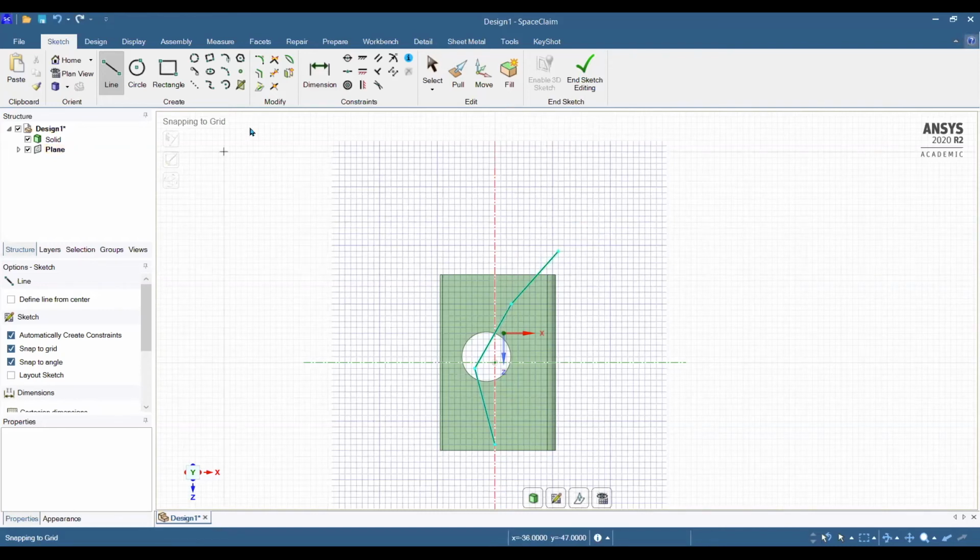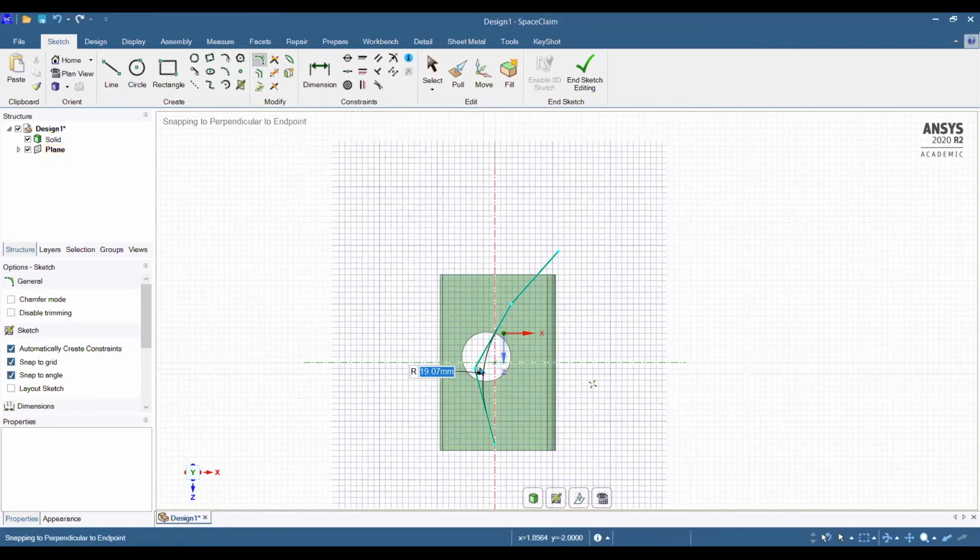And I want to add a curve to these lines. So I'm just going to go to modify, and I'm going to do create a rounded corner. Click on this, and wherever corners there are, I'm just going to click. Click once, and then I can just move my mouse a bit to create my bended corner, like so. Kind of gets a bit messy, but that's something you can do.